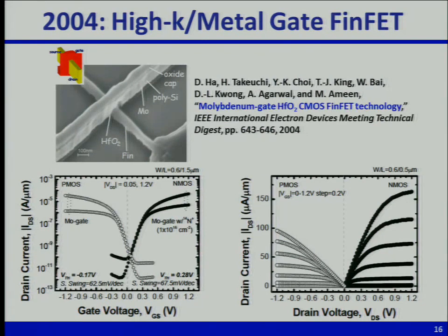It's more difficult because you have a vertical structure. Well, it turns out that you can implant the dopants into the fin and do some thermal annealing to diffuse it to be pretty uniform. It turns out that if you look at the volume, okay, so this might be a good exercise. Look at the volume of the channel of a FinFET. Okay, so let's do a little exercise here.